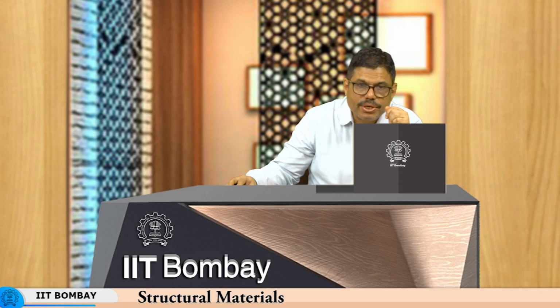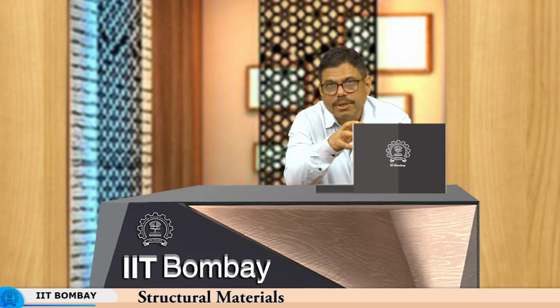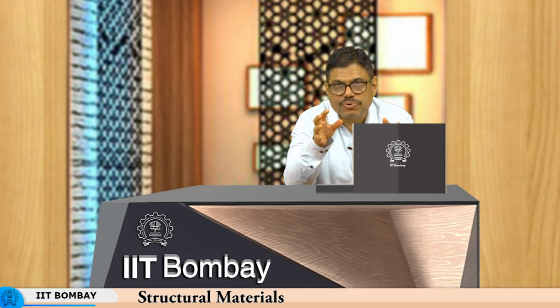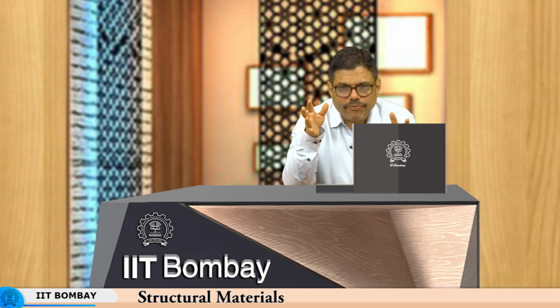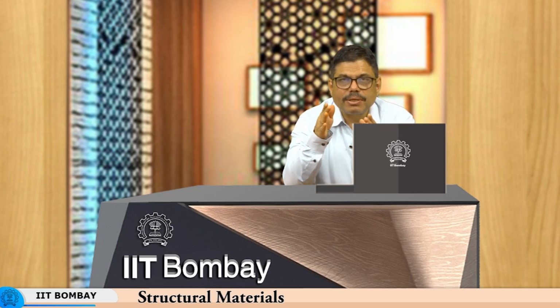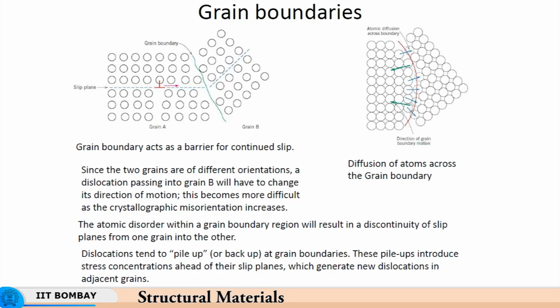Due to so-called dislocation climb at high temperature, where these atoms are able to diffuse out, a dislocation can go to some other plane as a result. Vacancies, for example, will help this kind of diffusion of atoms. These vacancies are point defects, and then there are many interstitials which diffuse due to high temperature. So again, the dynamics of interaction between the dislocations and the interstitial atoms keeps on changing with temperature.